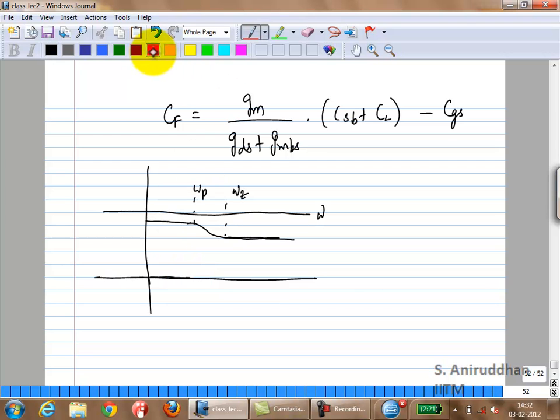In this case, you are going to get something like this, because now the zero is a left half plane zero. Correct? So the phase will go back to 0. Now depending on the distance between omega p and omega z before adding Cs, this peak will shift, because if this moves higher, then this will peak even more, or it will dip even more.